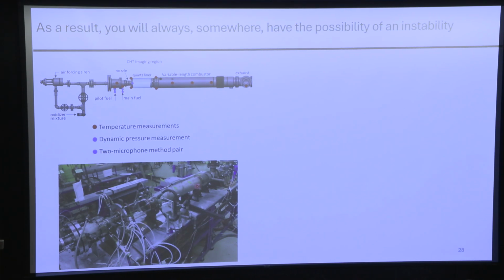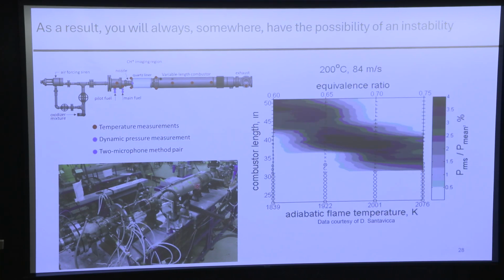And so one of the things we always do, because you're changing the length, you're sweeping through, in this combustor, 4 different acoustic modes. And so you can really work out the flame in a lot of different ways by changing the acoustics of the system. And so Don's group took this really nice map of one of their injectors.